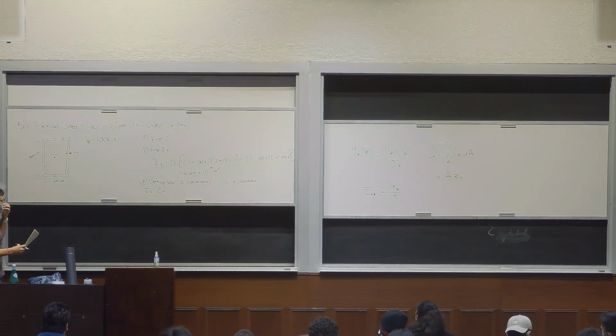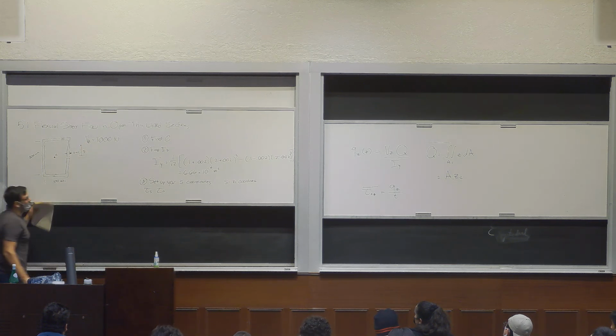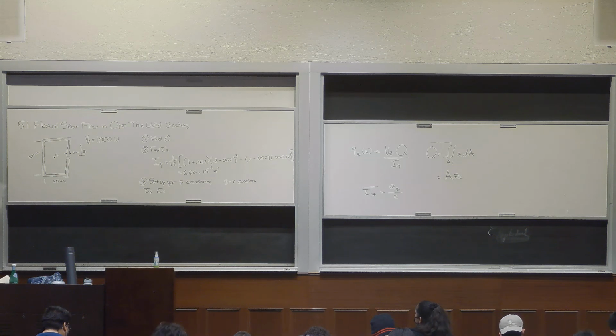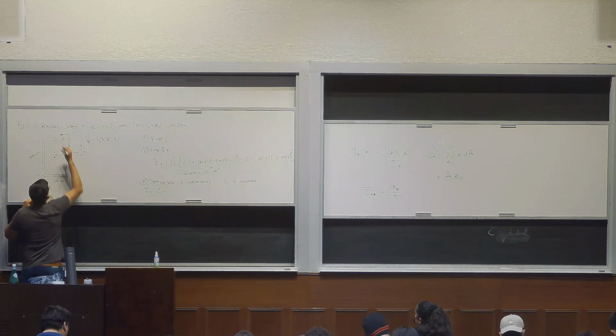All right, so now we have to set up our S coordinates, okay? And the way you do that for these open, thin-walled sections, so remember it's open, you'll start at one of these open ends and you'll set up your first S coordinate, okay? So in this specific case, we'll go here and set up S1. So S1 starts right there and it points up, okay? Whenever S changes directions, we're going to set up a different coordinate system, S2. Well, it doesn't have to just change directions, right?